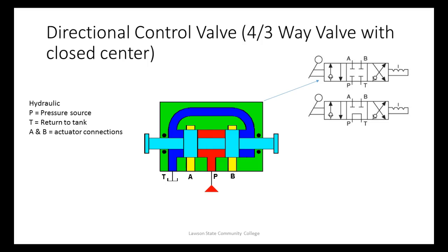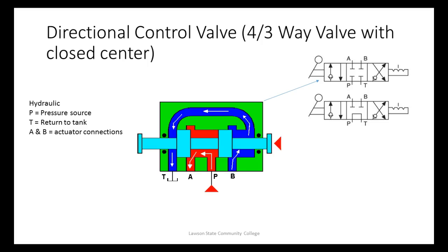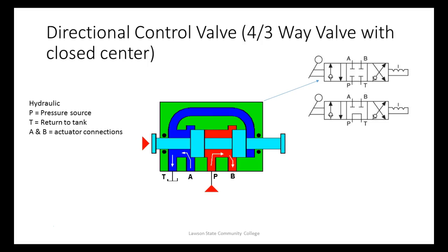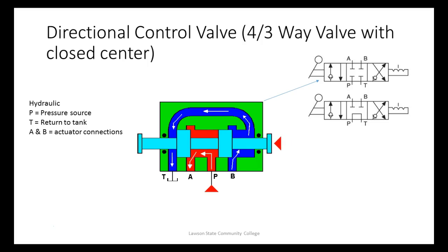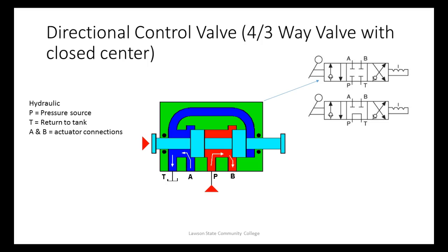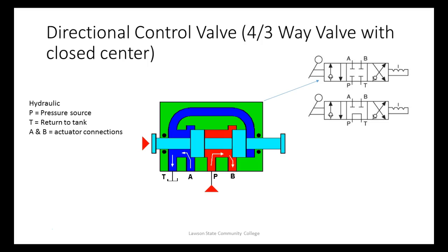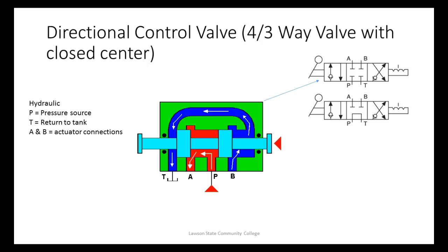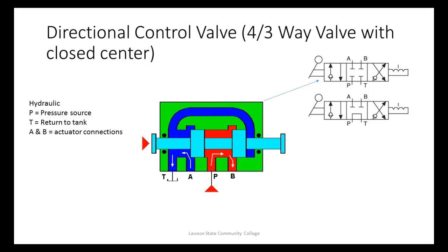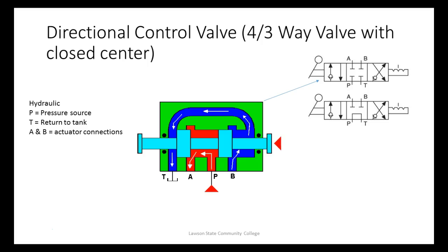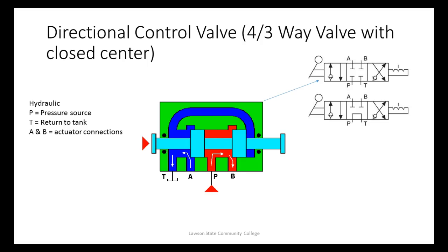Hydraulics, you would not be able to move that actuator. It would be locked in its position. Like I was talking about a backhoe, what can they do on that thing? They can stop it anywhere, and it just locks position. If you go out there, you couldn't pick it up and you couldn't pick it down. Pneumatics, by the way, even a closed center, you would be able to move it a little bit because you can compress it a little bit, right? So this is another problem we have with pneumatics: we can't lock the actuator in mid stroke. We can, but it still might move a little bit because we can compress it.